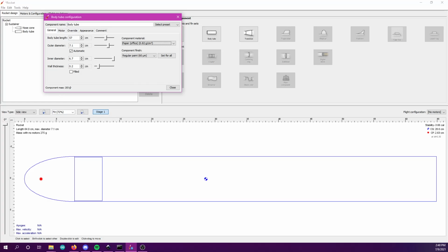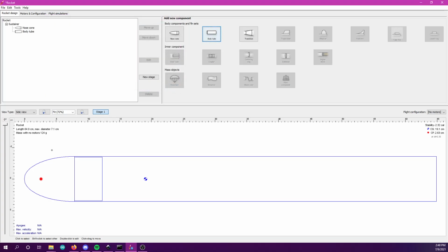It might be a little too thick. Let me go down to about 0.05. See that mass dropped to where it's reasonable, about 50 grams. So keep an eye on that. The mass will give you a good guideline of whether you're getting the dimensions and the material right. Again, if we don't have anything on this little part tree selected, we don't get the extra options.